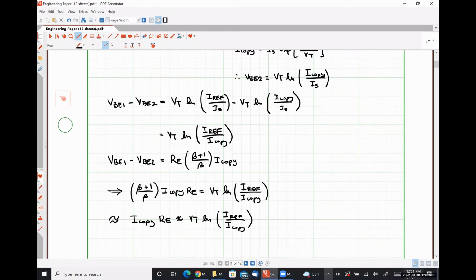So this circuit is used to take large-ish, by that I mean on the order of milliamp, input or reference currents, and convert them to steady integrated circuit biasing currents on the order of tens of microamperes. So it takes largish currents and makes them small and stable to bias microelectronic circuits. And that's what this transfer function tells us.